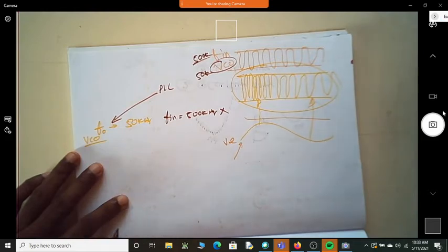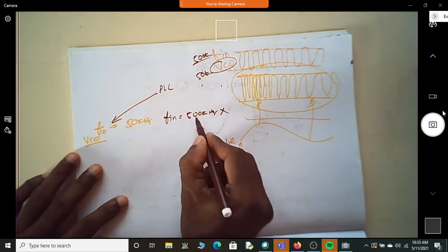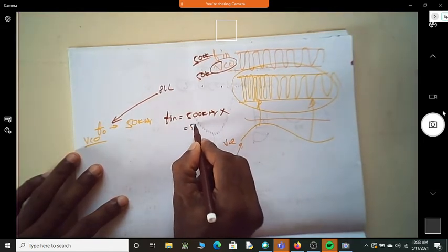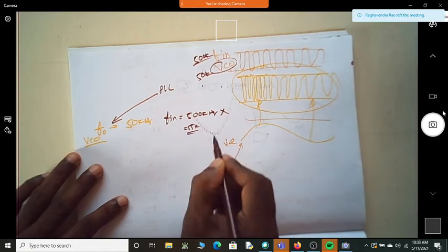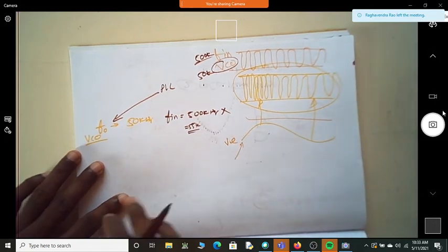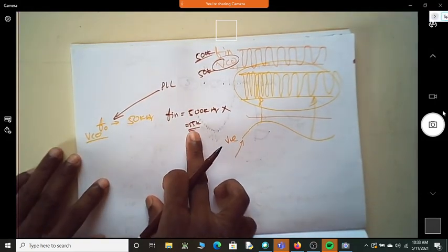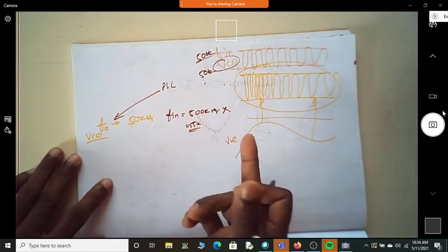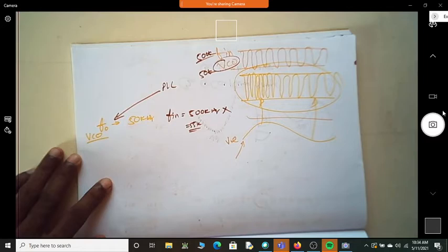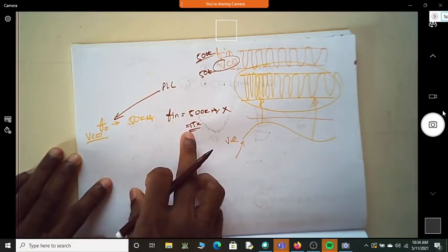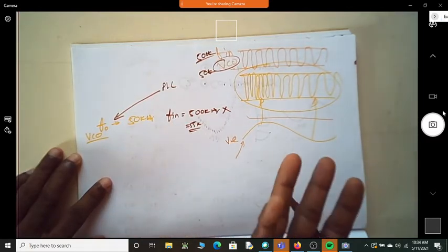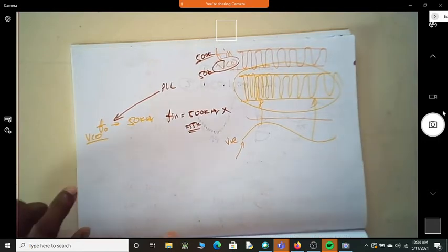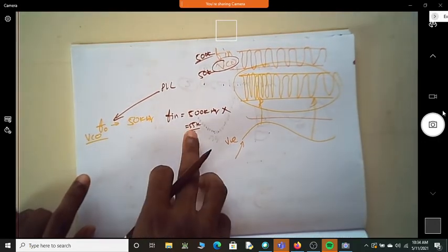I'm unable to capture it, as it is too far away. So I need to make sure that it is in the vicinity, maybe 55 kilohertz. If your incoming frequency is 55 kilohertz and the free-running frequency is 50 kilohertz, it can capture that so that it can track it. At the time of capturing, it has been captured.